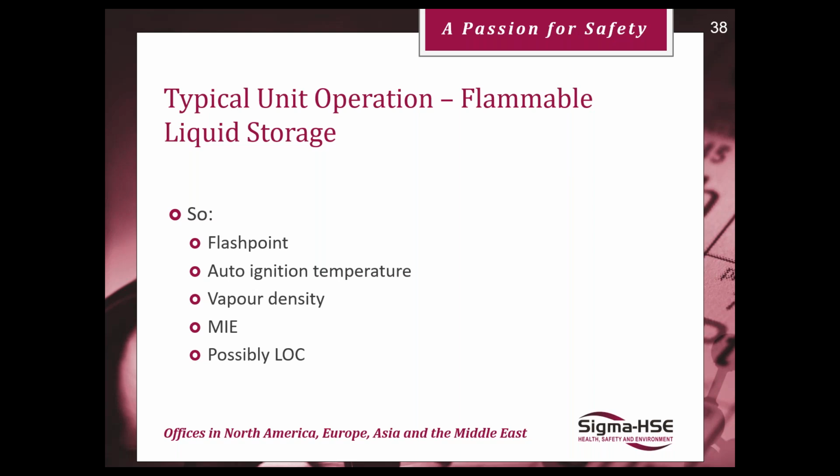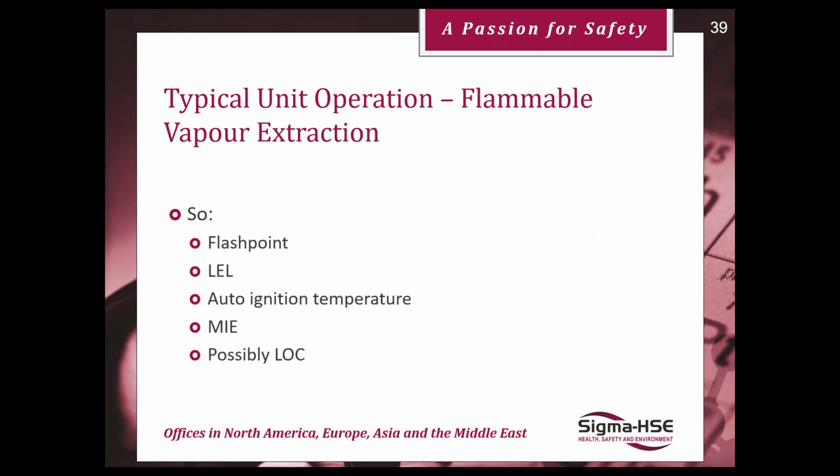Or we could inert, which is becoming increasingly common in flammable liquid storages. But having said that, there are still plenty of atmospheric storage vessels out there. And extraction systems on flammable vapours or on liquid storage tanks are again becoming more and more common, primarily because of environmental legislation.